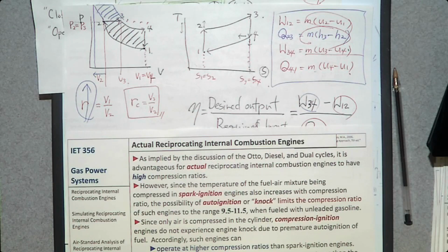So where do we use a diesel engine? In an airplane? No. Usually in a dump truck or a container ship. Between the dump truck and the container ship, we focus on fuel efficiency, because you may spend maybe $100,000 per day just for the fuel. So in that case, we are trying to increase the compression ratio as high as possible.